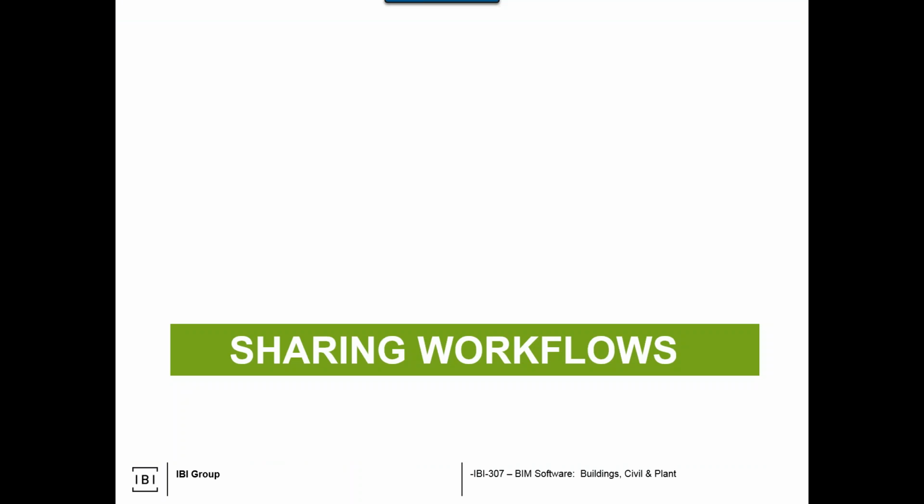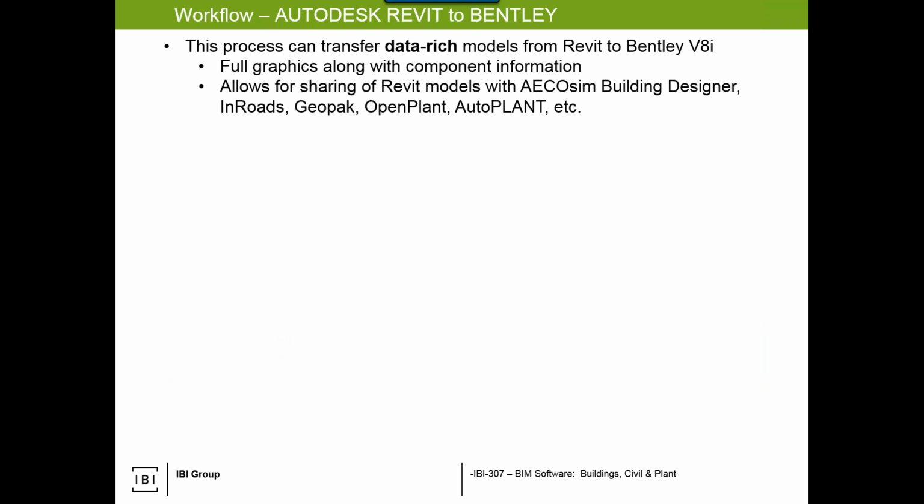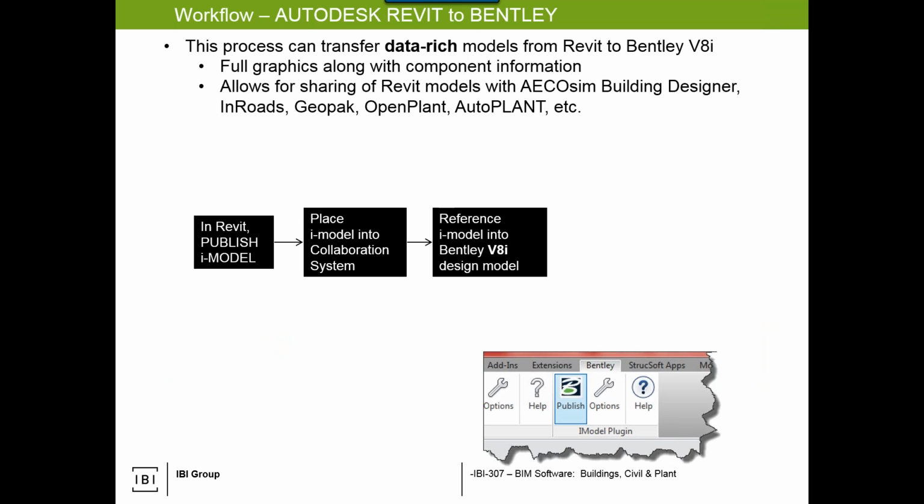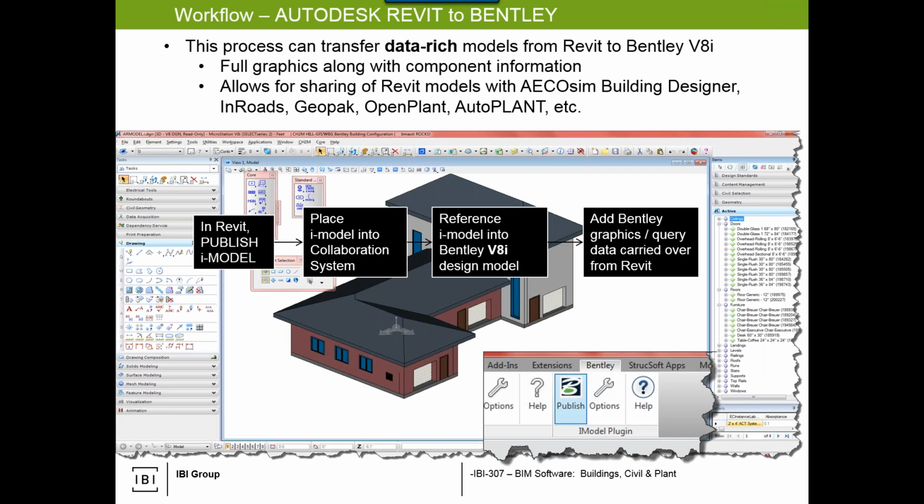So just to close, a couple concepts on sharing, and I'm not going to dwell on these. We can spend hours on these alone. But if you had an Autodesk project, a Revit project that had to go into Bentley, quite literally, there's a publish button inside the Revit interface. It creates an iModel, and it makes it available for others to use inside the Bentley world. And I'm using a common graphic model for all of these, but what this is showing is a Revit model inside Bentley, plain and simple. Push a couple buttons, whatever it sees in Revit, it exposes into Bentley.